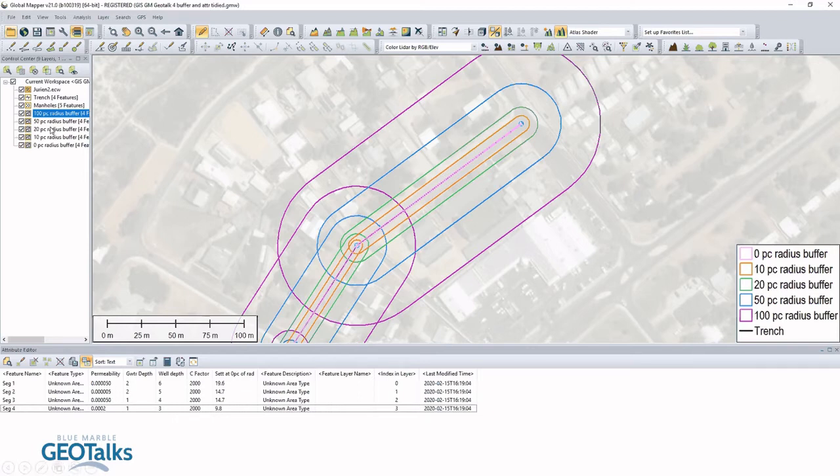The next step might seem surprising or unnecessary, but it comes in handy later. You see how the buffer ends clash around here. This is not realistic because other overlapping well points do not cause double the settlement where they overlap. So I'm going to manually clean up these, as it will make the settlement slopes, which I generate later, look very ugly. It's not entirely necessary to manually tidy them up.